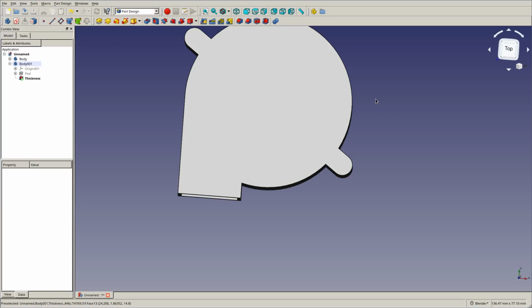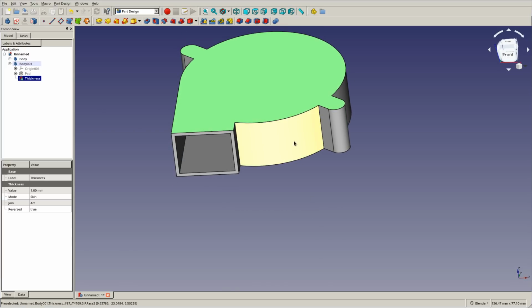However, it's going to work for a part this simple, but when you make complicated parts with many steps, and you're not sure about the final order of the final features, and if you still think that you're going to shuffle things around after, mapping sketches to faces like this is kind of dangerous, because let's say we change our sketch and there's 1 more face in the pad.